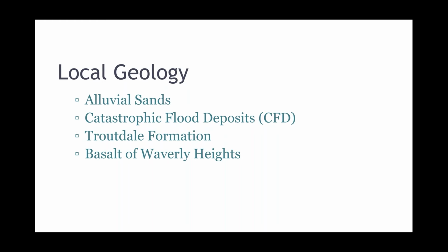More specific to the site and from the top down, the 4 primary strata that were present, starting at the mud line, you have alluvial sands. These are very low shear strength, very weak, recent deposits. We're not going to spend much time on them, basically because through the design of the permanent works, this material is really neglected in the design. If the river put it there, the river can take it away. It's sort of the easy way to look at it.